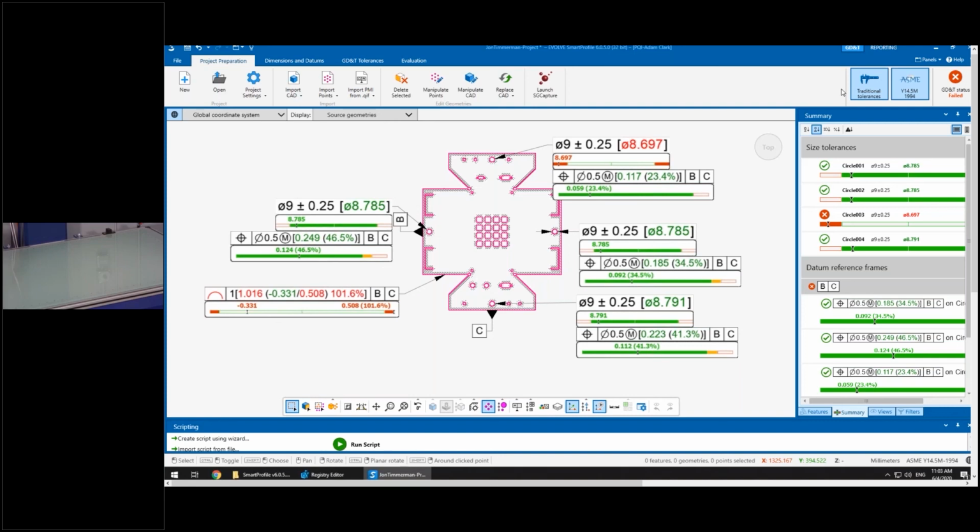But the ideal way to use it is, again, to use a known standard. You could even use a caliper if you want. You could say, I want to get these overalls and my diameters as close to this caliper as possible. You could put your part on the table and start typing in. Start off with 0.1, which is a good value to start with. Did that give you a better or worse number than you're expecting? And then you can go inverse from there to try and get that number to what you're hoping for.